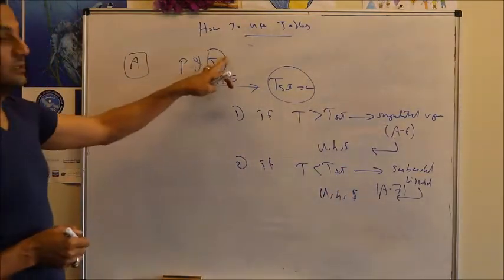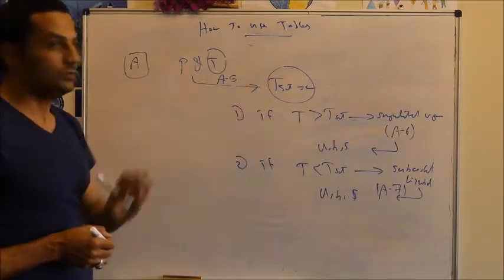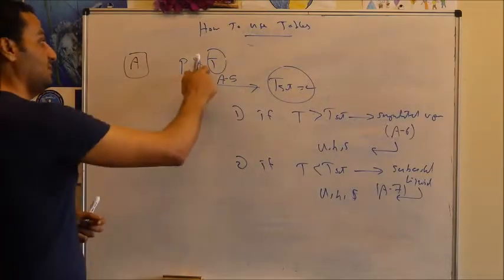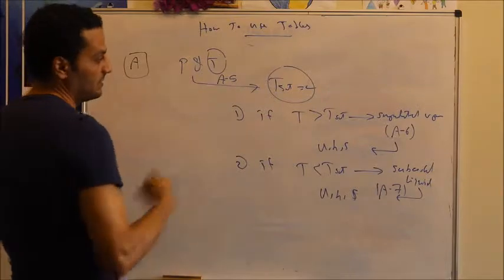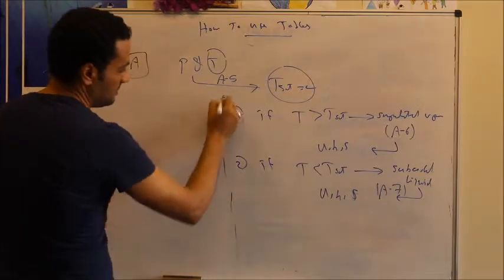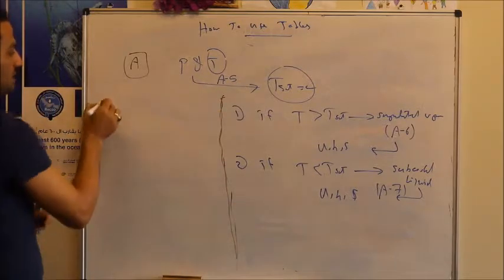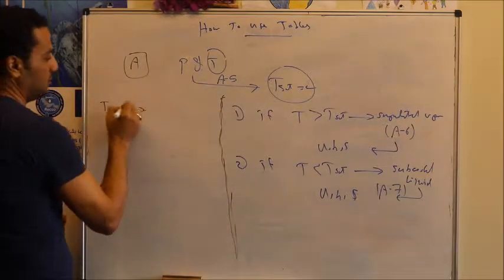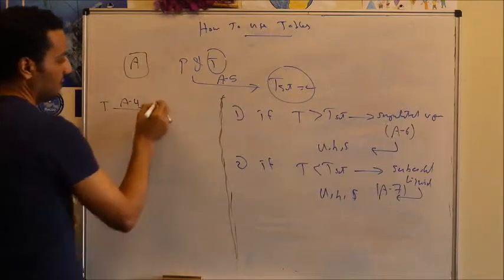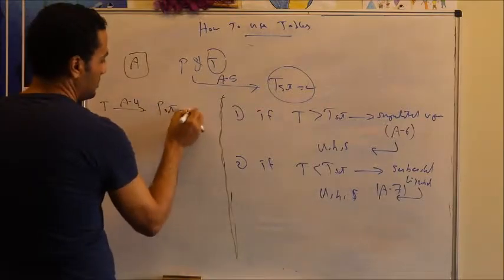In this case, pressure and temperature are given. I took pressure and went to table A5. Can I take temperature and go to table A4? Yes, exactly the same procedure. So it's an option for you. You can either follow this option, or you can just take the temperature and go to table A4. In this case, I will get the saturation pressure.